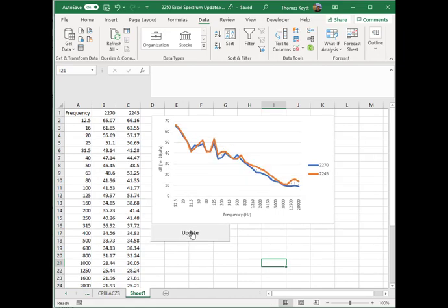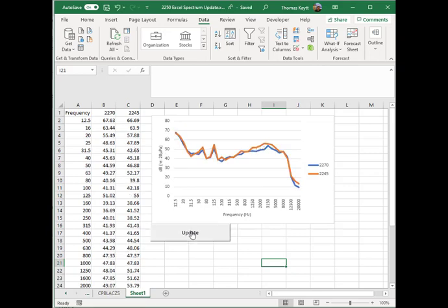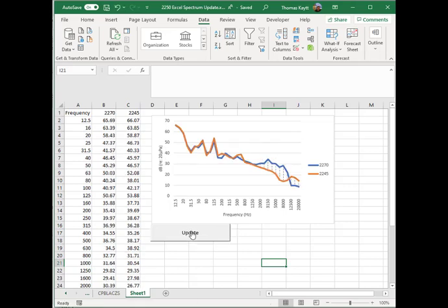I actually built this demo explicitly for a customer who wanted to use their sound level meter to tune an architectural sound masking system. With this system, they were able to monitor live noise levels from their system while 100 feet or more from the sound level meter, making adjustments to the noise generator EQ and overlaying the meter's results with their pass-fail criterion.